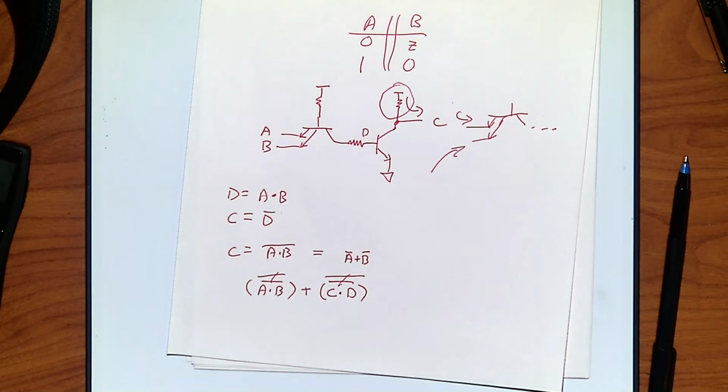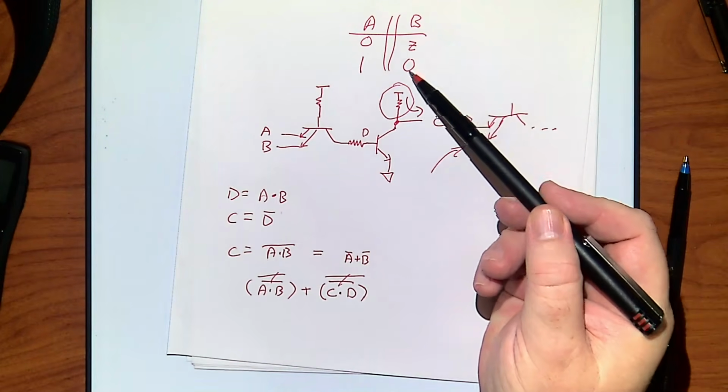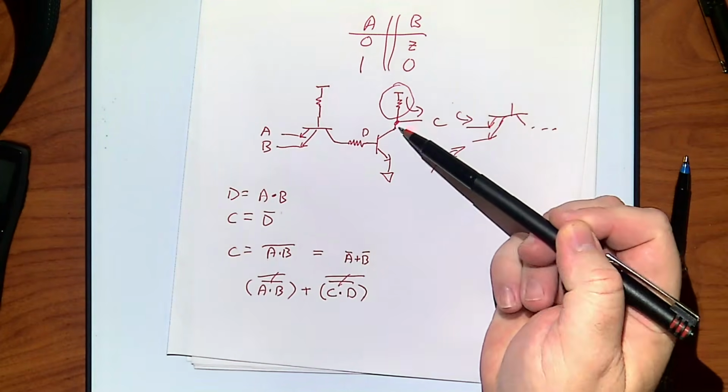So you have a high impedance instead of a lot of current, because there's no current being supplied. That device either gives you a ground or gives you a not connected. You have to hook something else outside to supply power. Because remember, in our logic chart up here, without that resistor, you either get a 0 or a Z coming out.